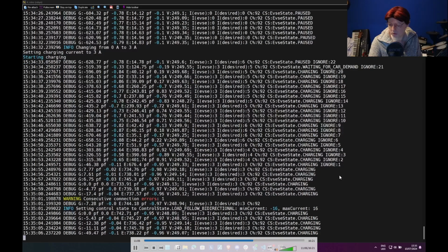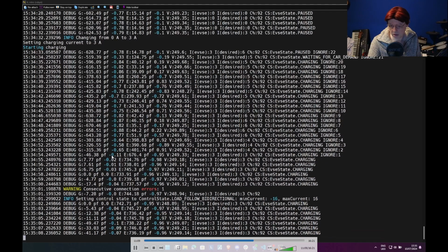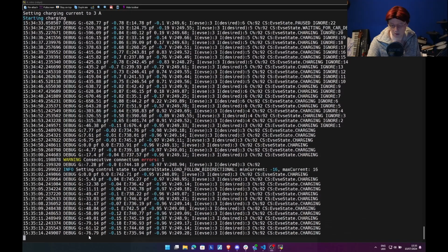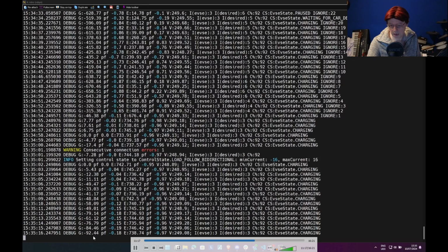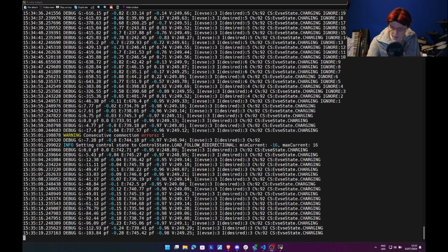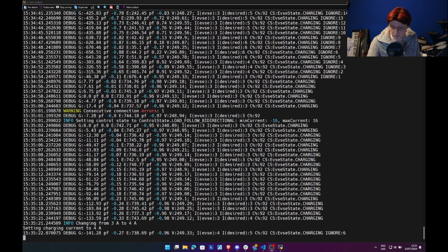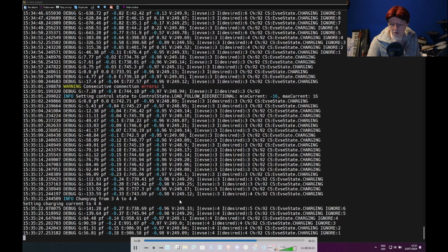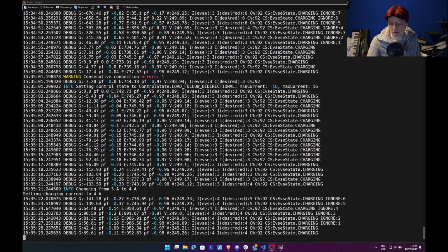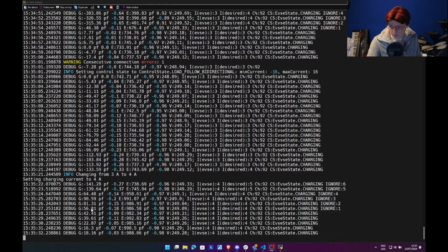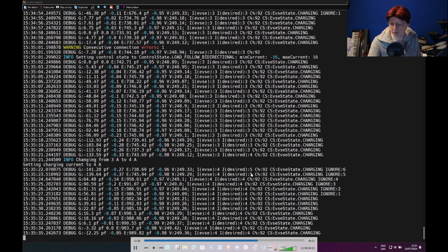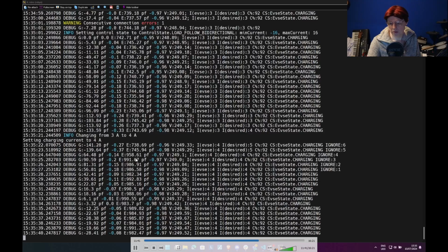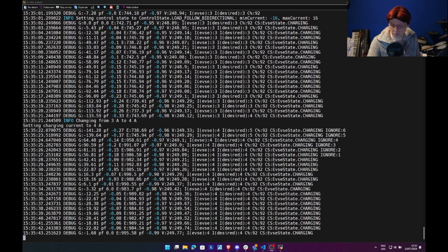So it takes 22 seconds before it will start, and it's starting, and you see that the power draw from the grid, we're still exporting a little bit. You can see that's going up, and I expect very soon, yeah, there we are. The software has decided now that it's better to take 4 amps rather than 3 amps. Now, it briefly went to a desired of 5. That's because it takes a little bit of time for the wallbox to respond.